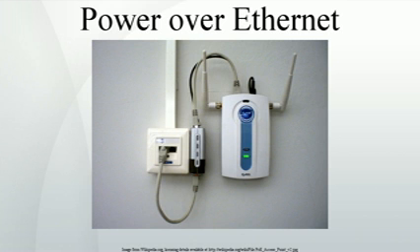Power management features and integration. Most advocates expect PoE to become a global long-term DC power cabling standard and replace wall-wart converters, which cannot be easily centrally managed, waste energy, are often poorly designed, and are easily vulnerable to damage from surges and brownouts. Critics of this approach argue that DC power is inherently less efficient than AC power due to the lower voltage, and this is made worse by the thin conductors of Ethernet.